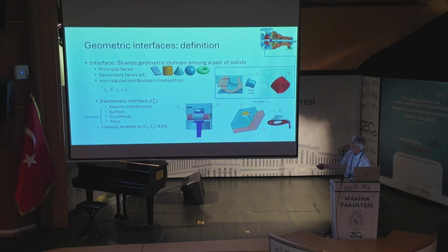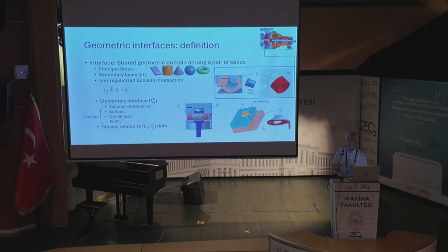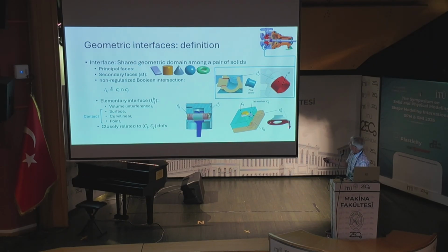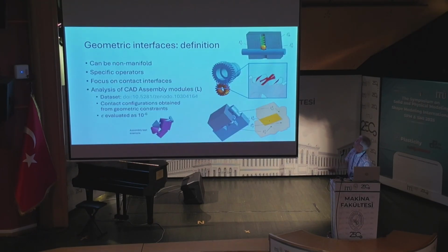You can see here the two pink areas. If the elementary surfaces are connected, what makes a difference is the difference in terms of geometric parameters. Here we have an example with this tab washer that has a contact area here and a contact area here. So it's two planar contacts, but not the same geometric parameters of the plane. And so it's two elementary interfaces.